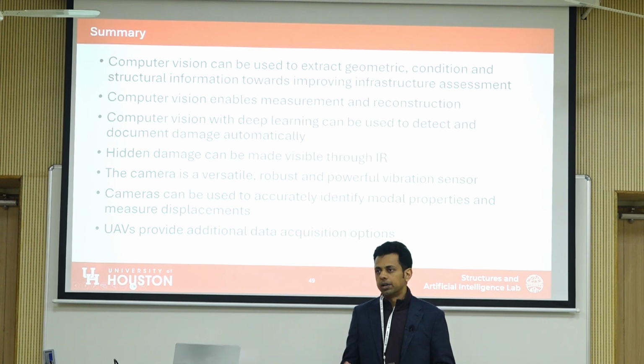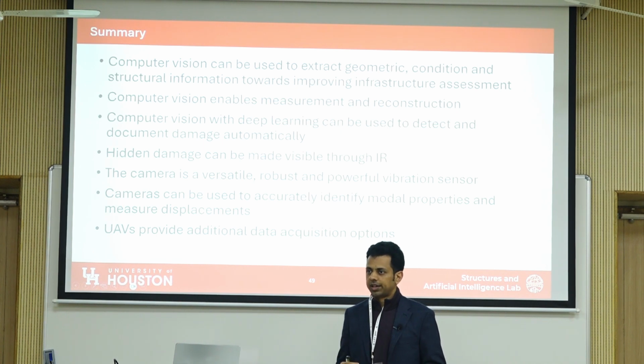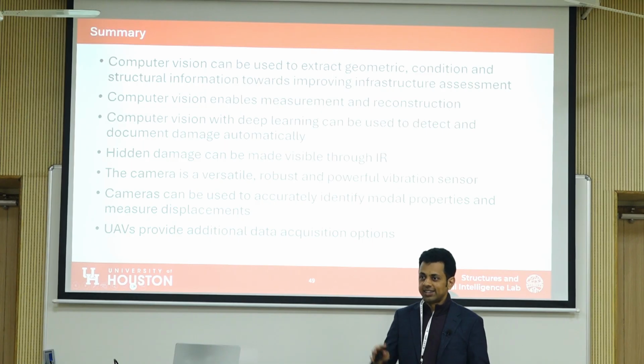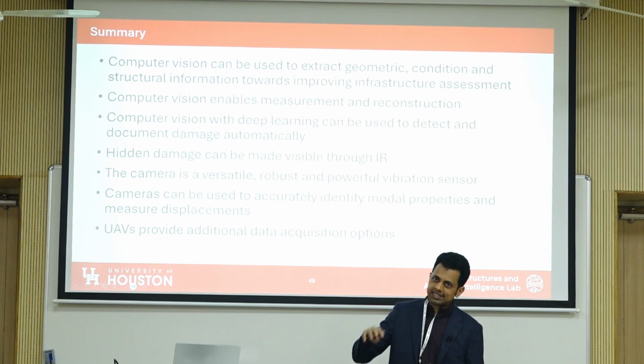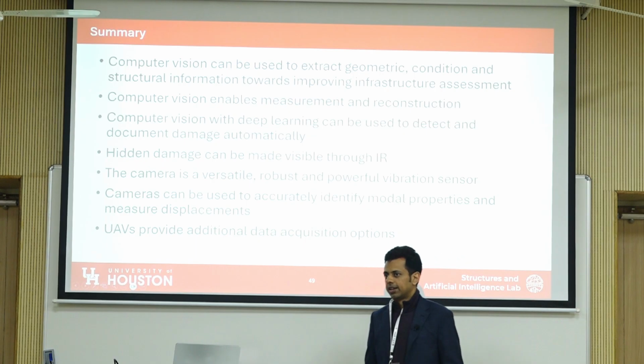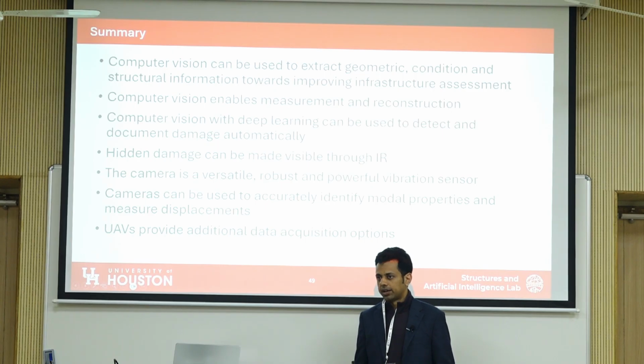Those are all practical challenges that you will encounter. If you can control it, more often than not, you don't have a choice, right? You have to pick a day, hoping with your best guess as to whether or not it'll rain, and then you go out and make the most of it. But if you can control it, then ideally you want cloud cover without rain, because that gives you uniform lighting for the whole structure.